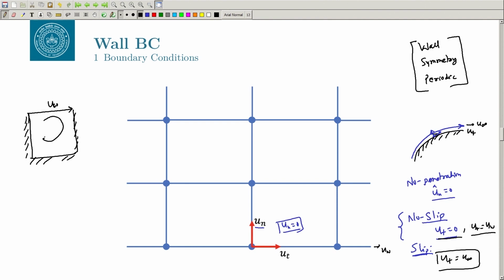And because of this a vortex forms. So, on all 4 walls you will be applying the no slip boundary condition, but in this case u equals 0, v equals 0 on three walls, and here u equals u wall and v equals 0. So, this is also no slip, because here the wall itself is moving. The no slip condition says that the particle acquires the velocity of the surface, that is all no slip means.